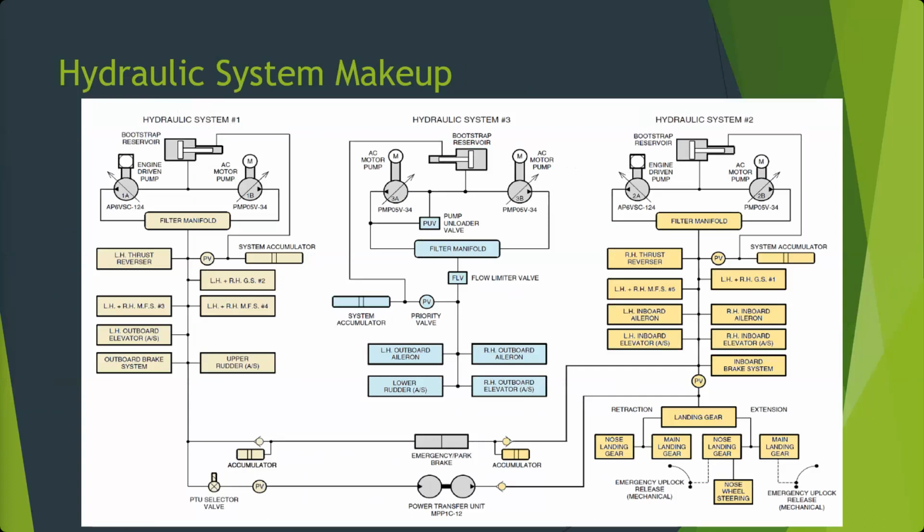In fact, the 727, that was really only meant for ground operation because it had 2 engine-driven pumps in one system and 2 electric pumps in the B system. They called them A, B, and standby. So the B system, you could run the 2 electric pumps on the ground, and then you could open that port to run the A system. And it was only supposed to be used on the ground, but it was a switch you could operate in flight.